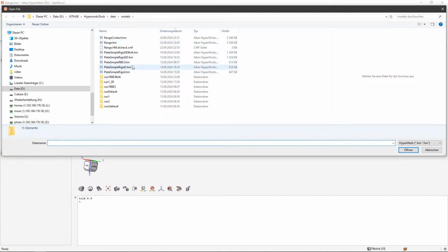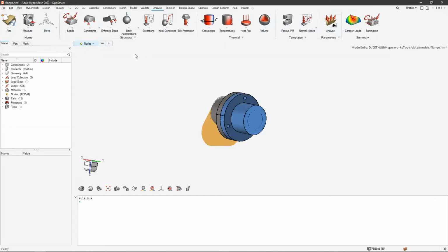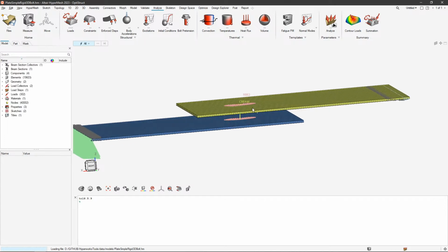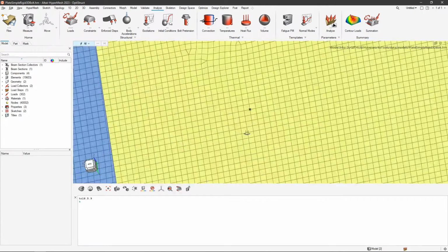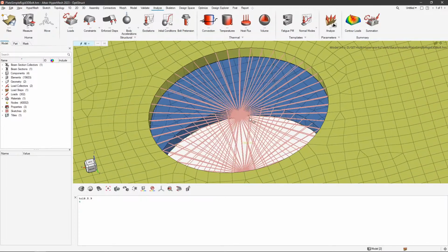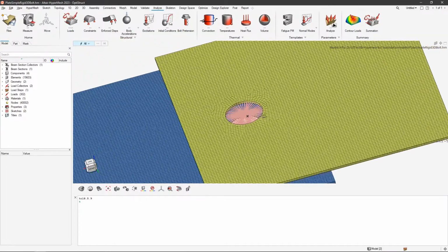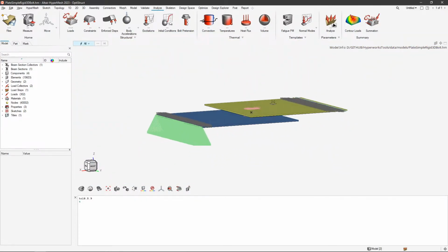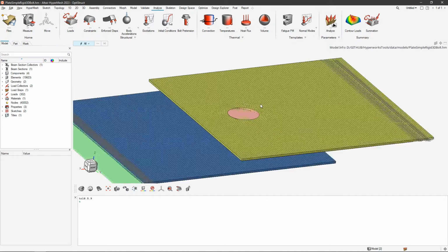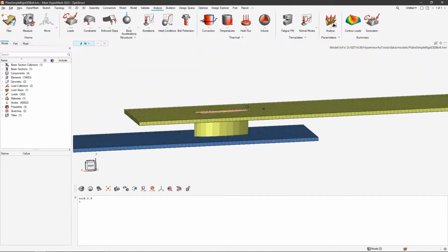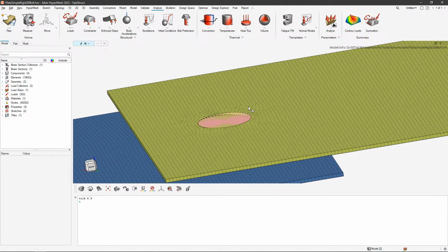There is this 3D bolt model, which has just a C-beam element between two master nodes of two rigids, right? And this 1D element is also having a cross section for sure. You can see that here. So this is the cross section of it, so it has a defined stiffness.